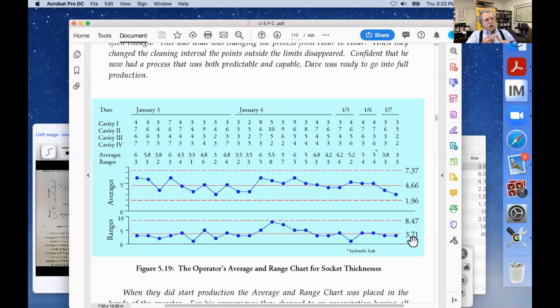You see how you collect the data, who charts the data, what purpose you're collecting the data for, and how you organize the data all depends on the context. And when the context changes, some of those things can be changed. So while this is generally not the best practice, it works here because they made the 4 cavities alike. Now, how can I say the 4 cavities are alike still? Well, if we got a cavity that started going bad, you get a big range, wouldn't you?